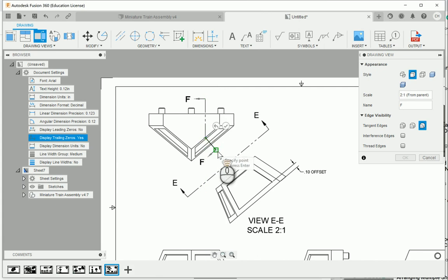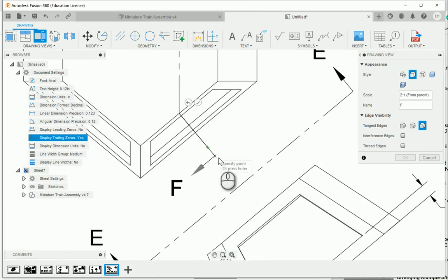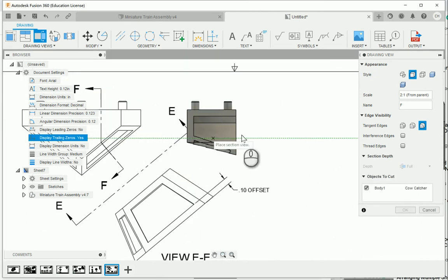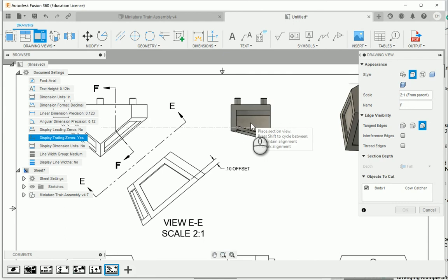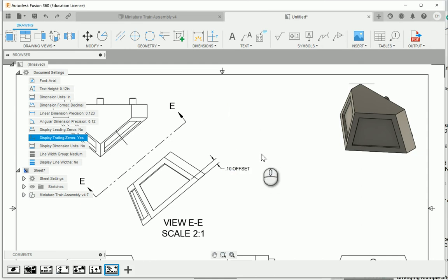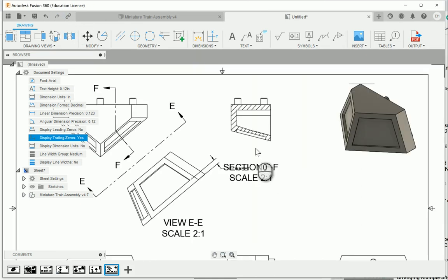And then I'm going to use this point, much like I did before. I'm not clicking, but I'm going to extend this out when I get that green dashed line to help me stay aligned. Clicking, hit the green check mark. Now I can go over here to the right to align, and now I can set up my section view. And if I need, moving the section note as needed.